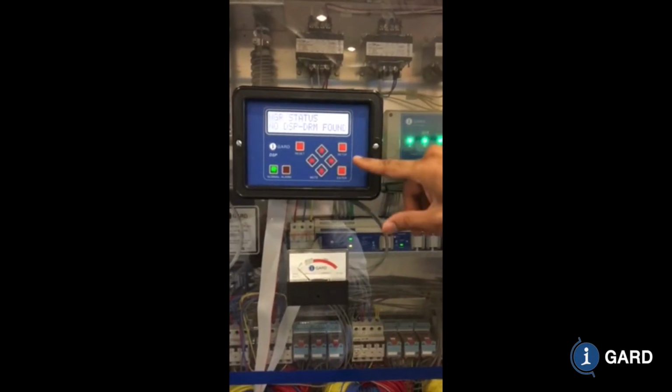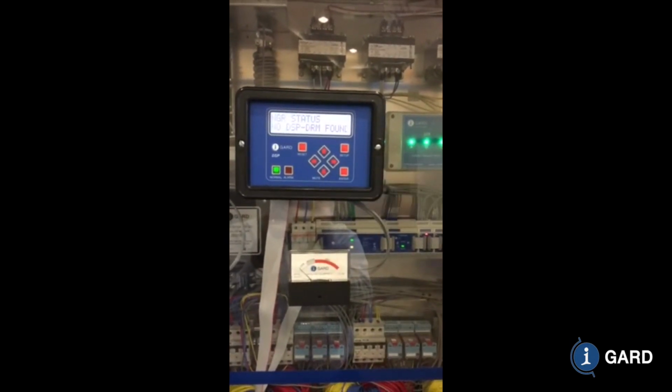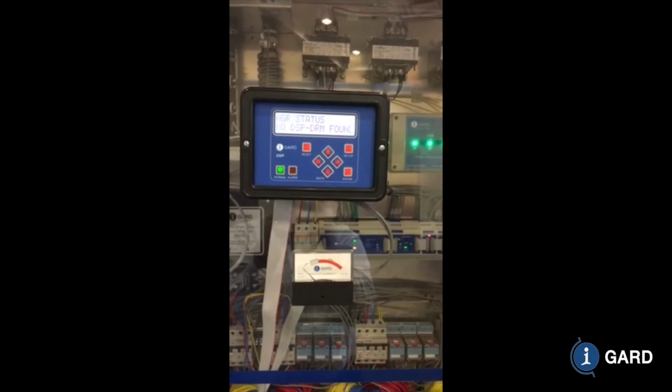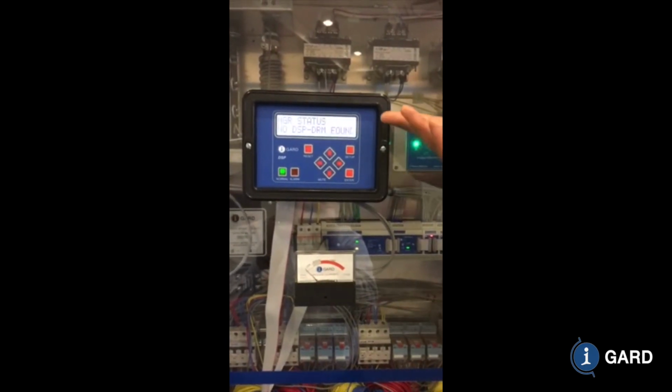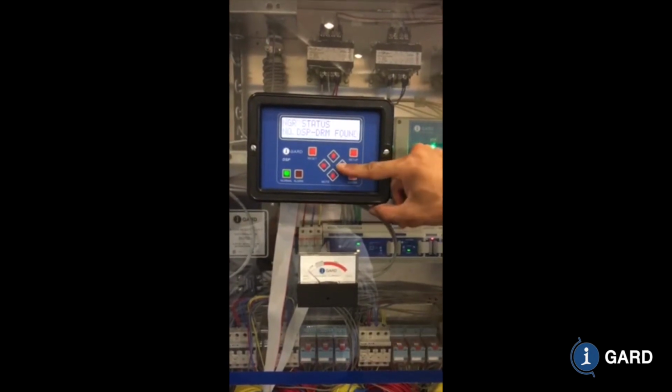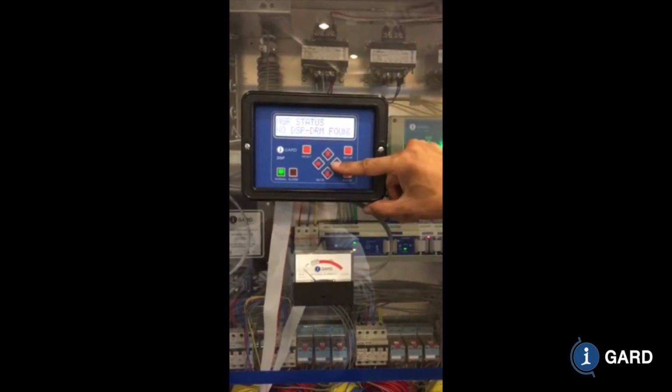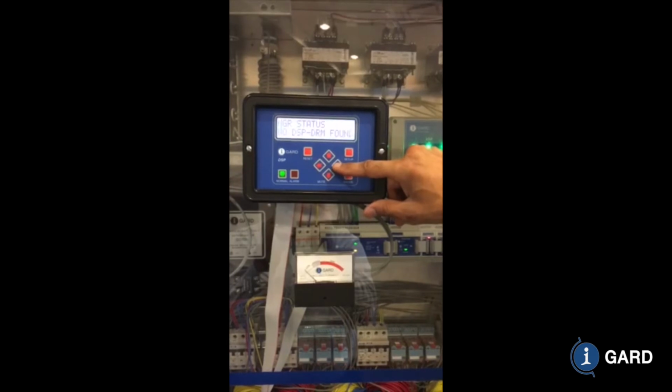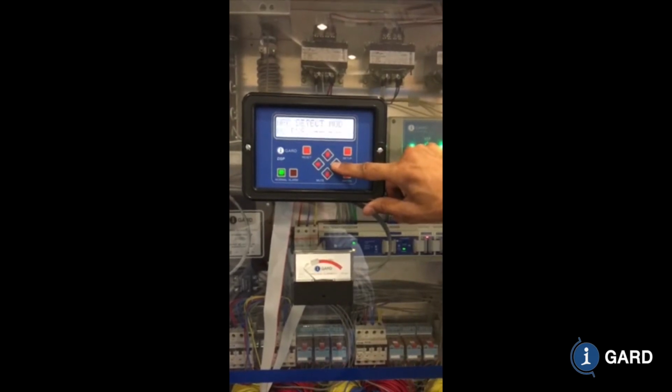And the next page after that is the DRM page, which does resistor monitoring. So you may or may not have resistor monitoring. Here's where you monitor the health of the resistor to see if everything's okay, because you don't want a system where the resistor becomes shorted or open circuit.